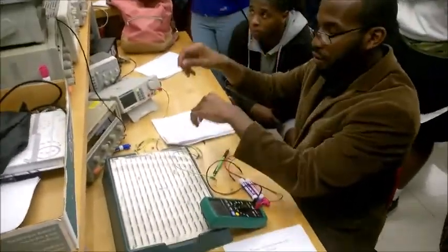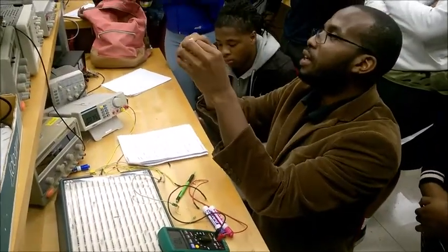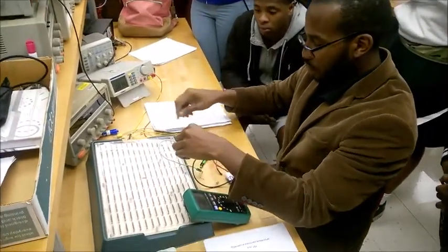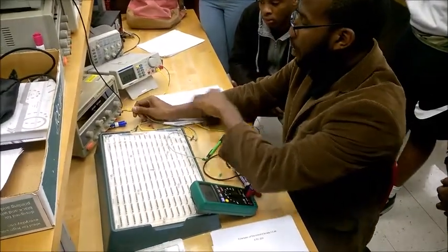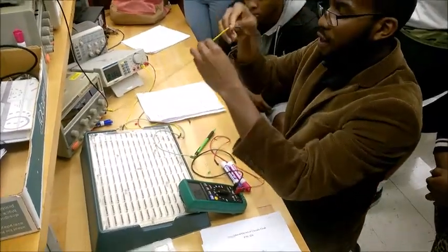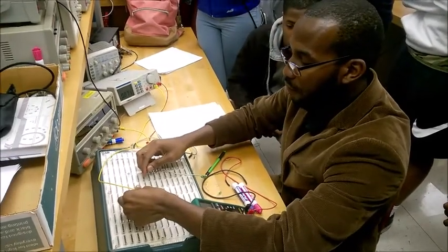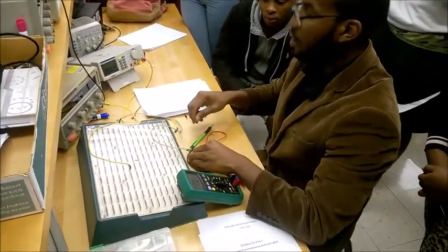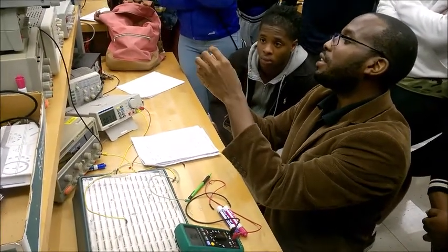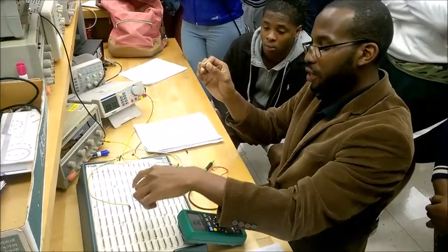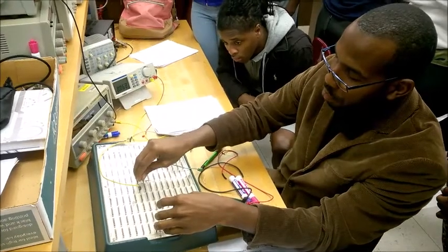Second thing I want you to do is to now construct a circuit. Now again, just like we have it on the board, we have the LED and the long leg is the positive. So the long leg is going to be connected to the supply. So I'll start with the positive. Again, we're using this fixed 5 volts here. So we push this yellow in this port here. So this is our positive, our supply. I'm going to just put it right here. And the positive is connected to the positive of the LED. Now the long leg is the positive of the LED. And the negative, the short leg, is connected to the resistor. So I need to put it in the same connection here with the resistor to make a connection.